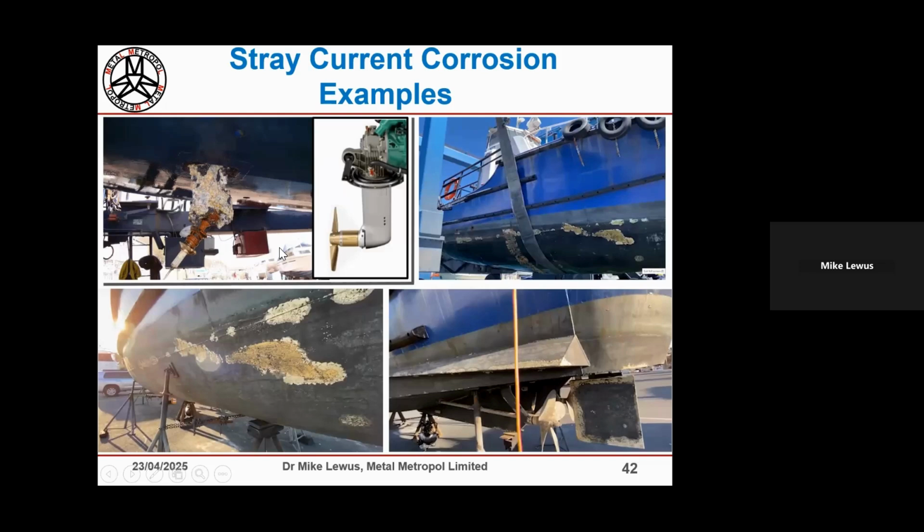But it puts in perspective, if there was no stray current corrosion, yes, there might be some galvanic corrosion, but rather than seeing the whole aluminium container, if you like, you might be replacing 1 or 2 small parts. But as a result of stray current corrosion, the whole thing's been completely destroyed. And another example is this aluminium boat hull, where the source of stray current wasn't identified.